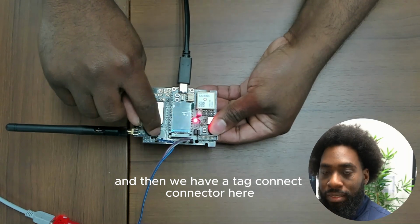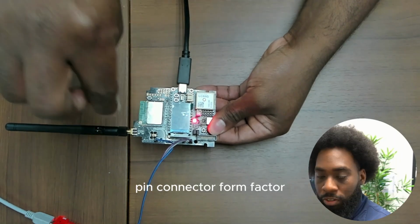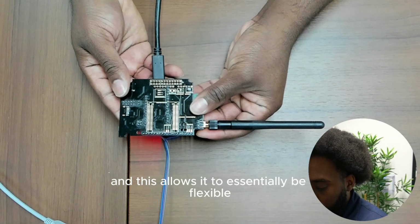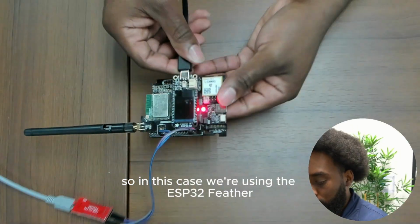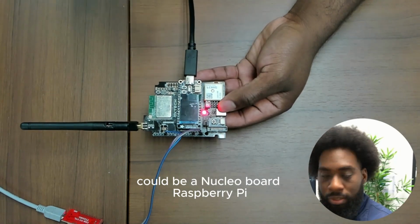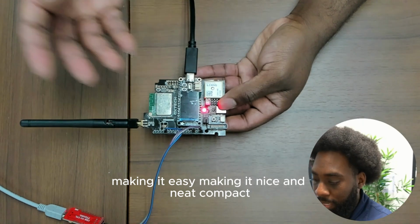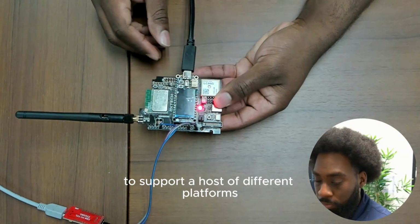Then we have a Tag-Connect connector here, which essentially does the same thing, just a simplified pin connector form factor. And then you'll see a host of header slots, and this allows it to be flexible in the platform that you want to stack onto or connect it to. So in this case, we're using the ESP32 Feather, but it could just as easily be an Arduino board, a Nucleo board, a Raspberry Pi, or a Silicon Labs dev board. Your options are there as far as what you want to connect it to, making it nice and neat, compact. We have the flexibility to support a host of different platforms.